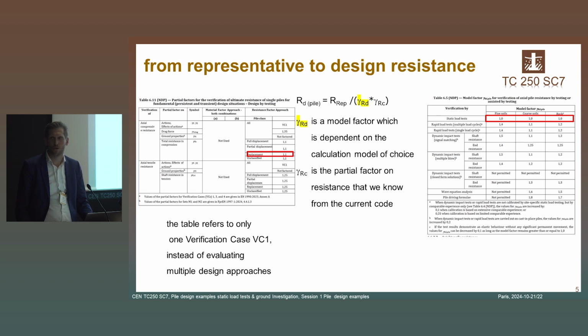In a calculation model, when you have a pile type that's heavily influenced by execution, you have to implement it in your calculation model. If you test a pile that's already made, you have this uncertainty actually covered by testing. So that's why all partial safety factors are here most probably the same. Same counts for the model factor.